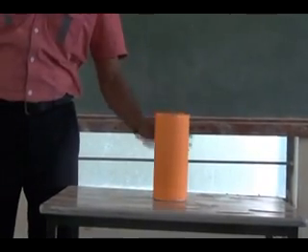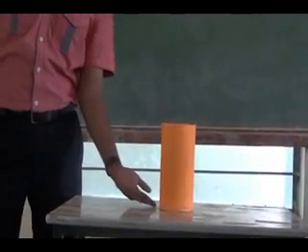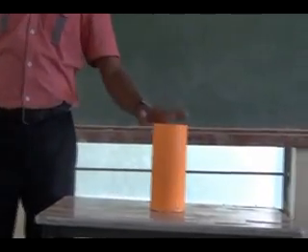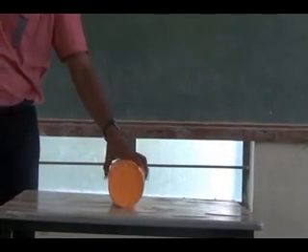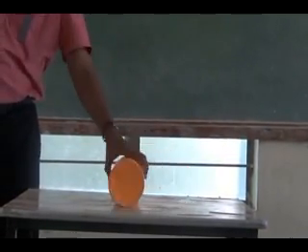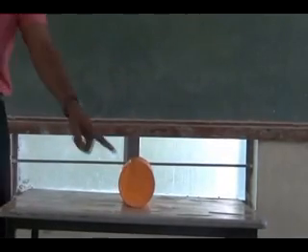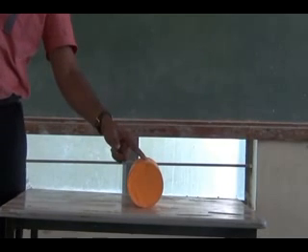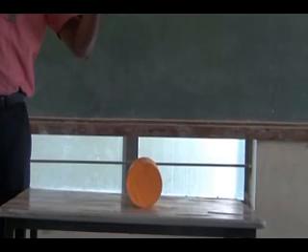Suppose the same solid is like this. I can say this is the top base, this is the bottom base. So this is the top base circle, this is the bottom base circle. Now the solid is here. So the position of the cutting plane is given 10 mm from the nearest base. So this is your nearest base here. From that, 10 mm on the axis, you have to mark the point.